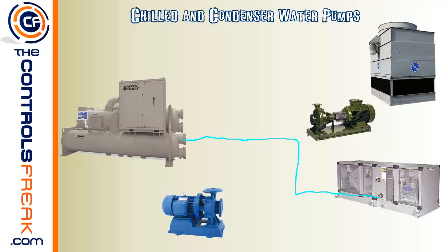And the reason why they do that, and it'll help you identify what piping is what, is that way when you fill this coil with water, you always want to have the outlet of the water coming out the top of the coil. The reason is you want this to fill up with water before trying to pull it out. If you were to supply this coil with water coming in from this direction, the water may not actually fill the coil and you'll get air in this coil, which would mean you're not going to get cooling on the upper portions of this coil if there was just air there, and water would flow in and then come down and get sucked out the bottom.